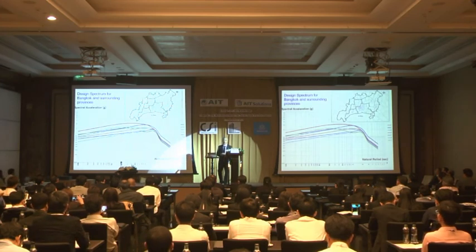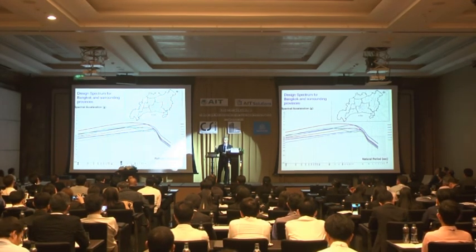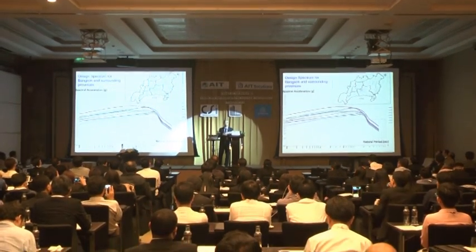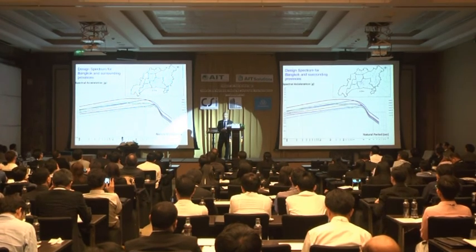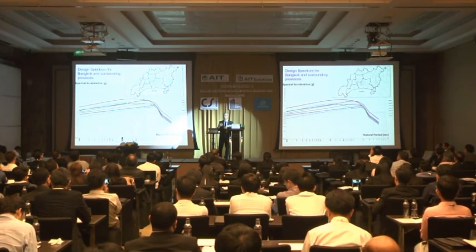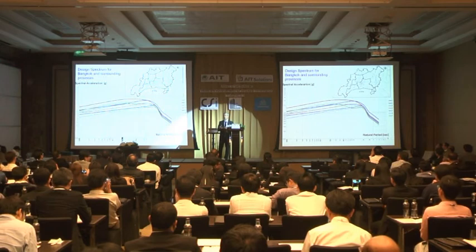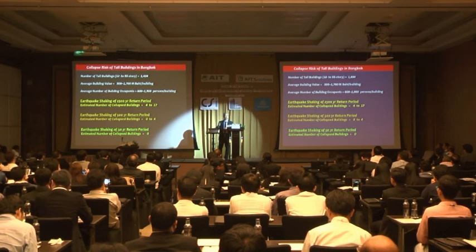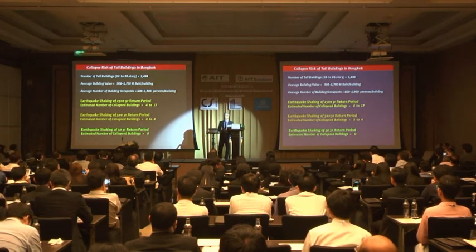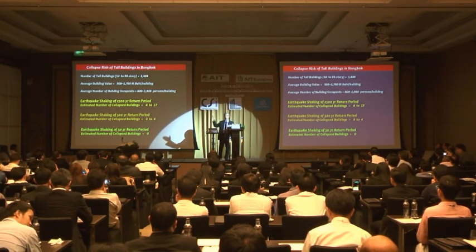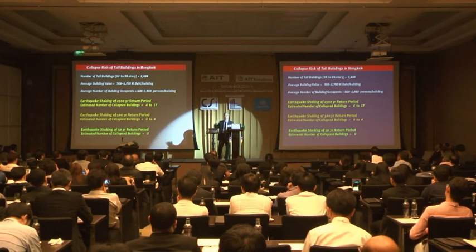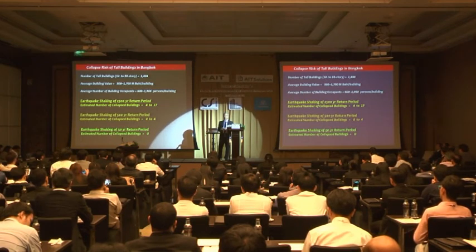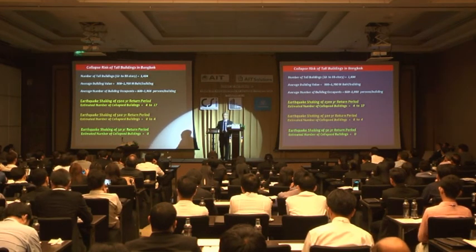Yeah, what can we do about this? This is a design spectrum for Bangkok. We are now working on a more accurate design spectrum, accounting for this basin effect and the long period nature of ground motion. That's for new buildings. But for existing buildings, we may have to develop a special approach to identify the weak tall buildings and do something about that. It has not been done yet, but that's something to do in the future.